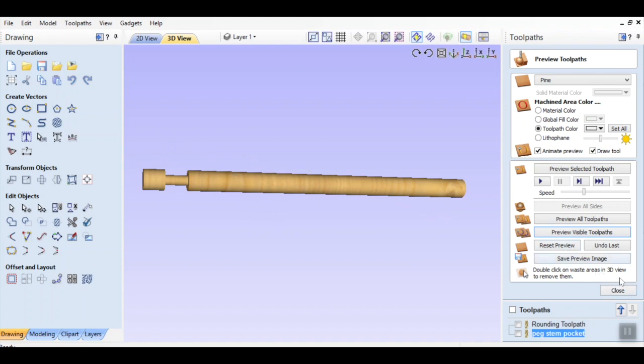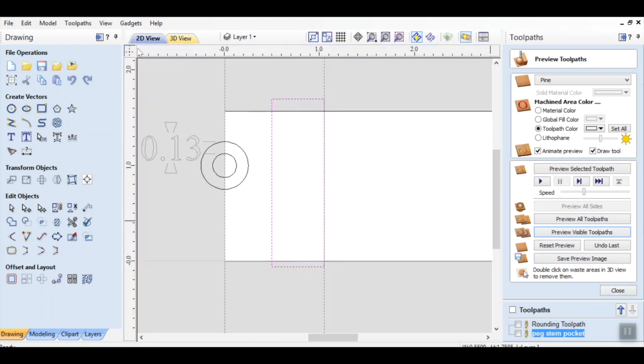So that's pretty cool. But you have to learn to think in two dimensions, like we did before, where we're machining this flat. And then it automatically wraps it around this dowel. So instead of moving in the Y direction, it becomes my rotational axis. So as it's cutting, it's rotating. So it doesn't go back and forth like it shows. This actually rotates, and as it rotates, that machining tool works its way down till you have a finished product right there.